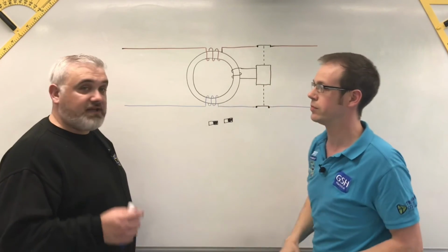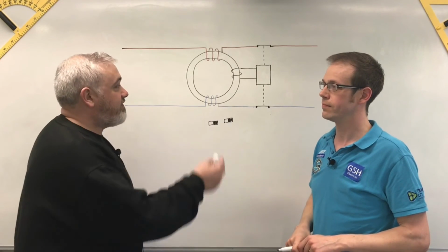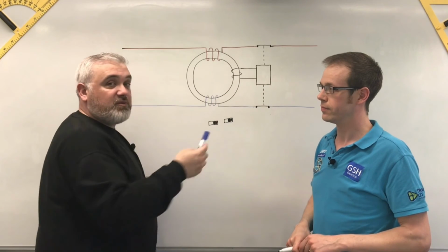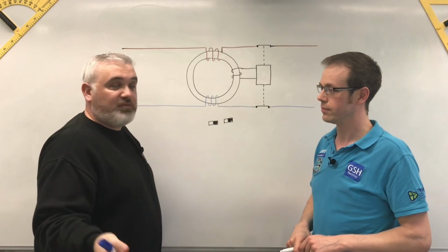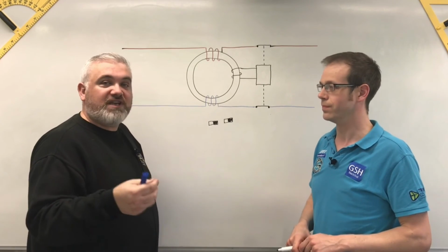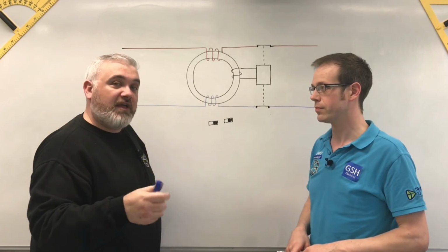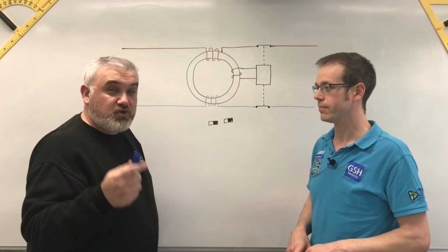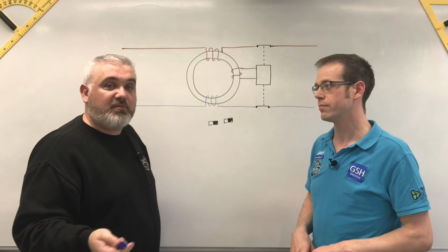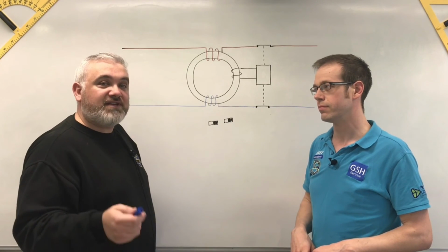Would you agree with that, Paul? Absolutely. So the devices themselves, if you look at the I delta N of a 30 milliamp RCD, if this device was the basic device for a 30 milliamp I delta N, the number of windings would be proportionate to the current that was needed to trip it. If you are saturating that device, you're effectively stunning or delaying the performance of the balance of the electromagnetic field. Henceforth, it will trip, but you need a huge current. As we saw in the video, we did a ramp test on a 30 milliamp RCD and it took 195 milliamps to take the device out.